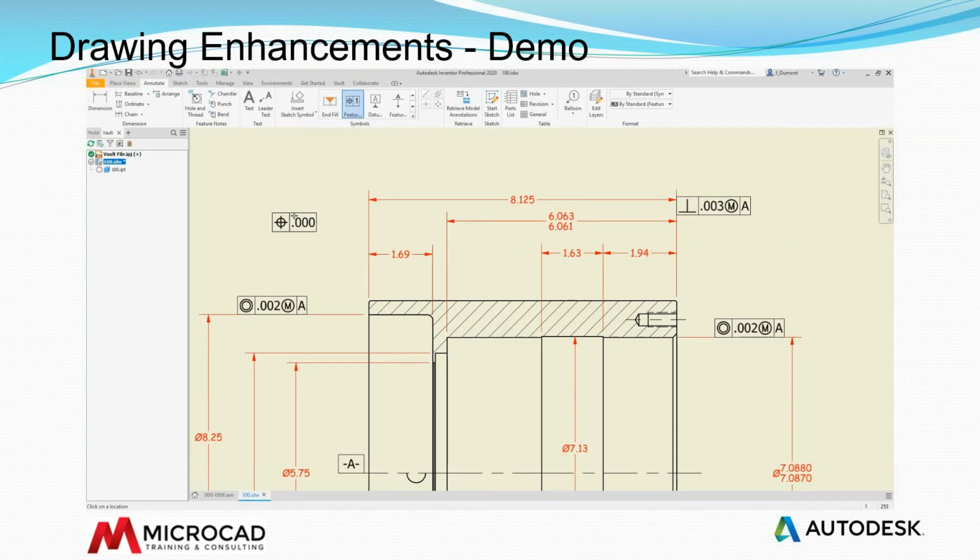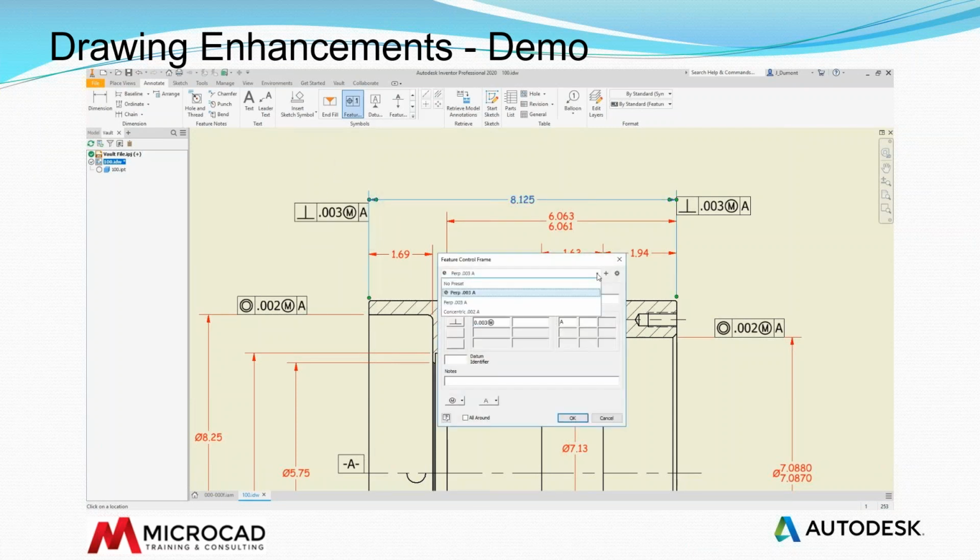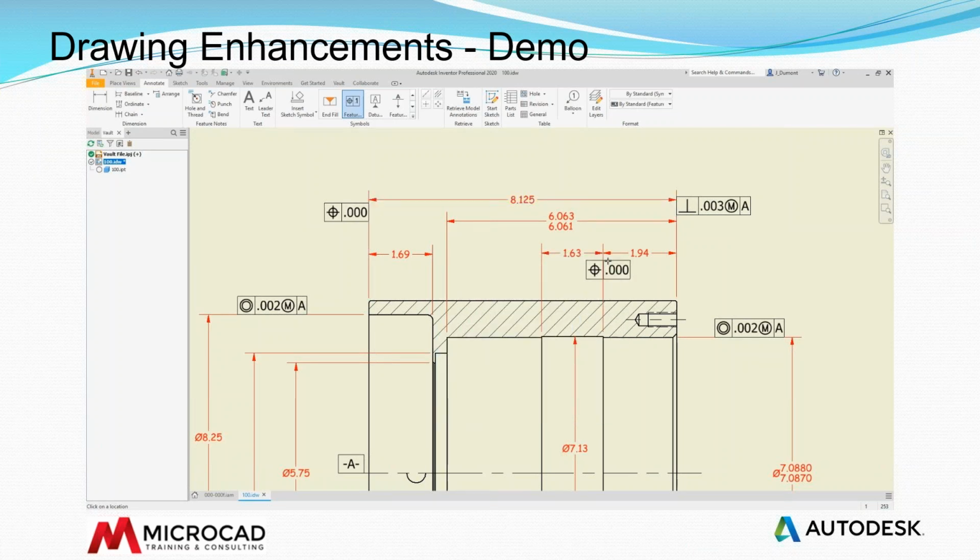So the next time I go and use a feature control frame, my presets will be there, and I have the ability to reuse them. Now the presets, by default, are user-specific, but they can be configured to be shared, put them on a network drive, so every user that's using Inventor can have use of these presets.